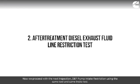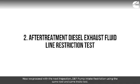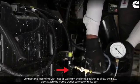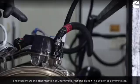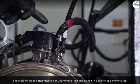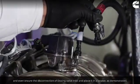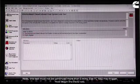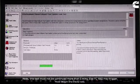Now, we proceed with the next inspection, DEF pump intake restriction, using the same tool and same INSITE test. Connect the incoming DEF lines as well, turn the knob position to allow the flow, also attach the pump outlet connector to its port, and even ensure the disconnection of the dosing valve inlet and place it in a beaker, as demonstrated. Note, this test must not be continued more than 5 minutes, else fault code 1682 may trigger. Now begin the INSITE test.